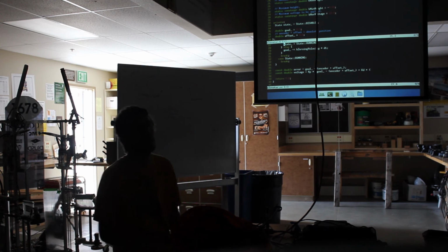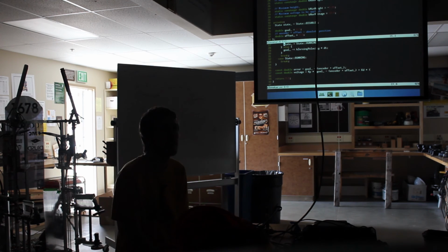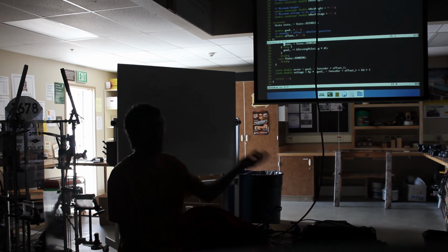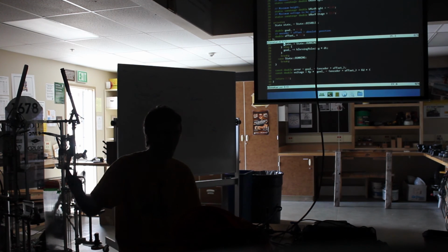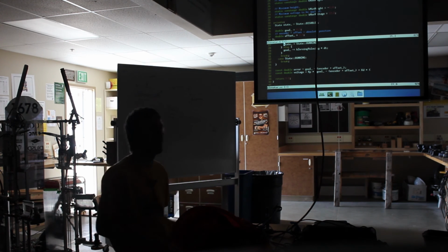Well, in the end, we want to take the elevator to a position, right? Yeah, but while you're lowering, the only knowledge that you have is you're going down at constant velocity, right? Sure, but if we want to implement it that way, then we need to design a lowering control loop and an operating control loop. Okay. So if we can just use our operating control loop to do our lowering, then we can save ourselves a lot of design work. So you can just generate a slowly moving system by just telling it to go down a little bit each time. Yeah. And that works pretty well.